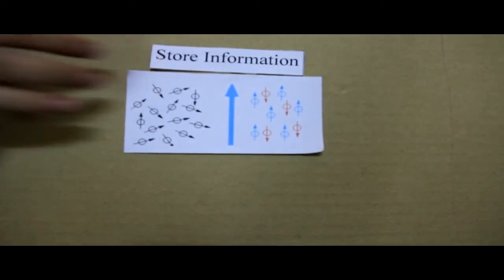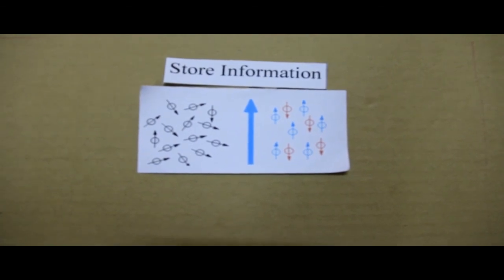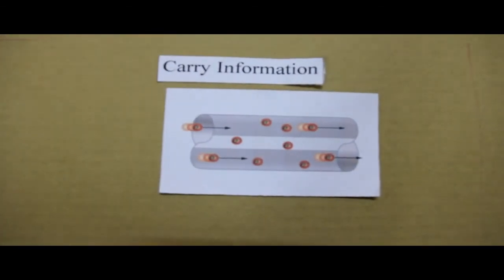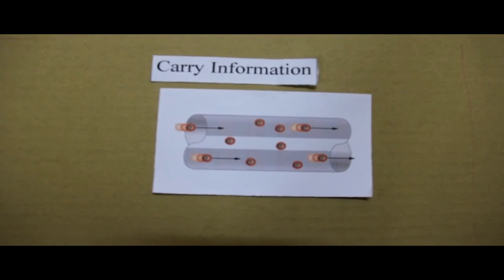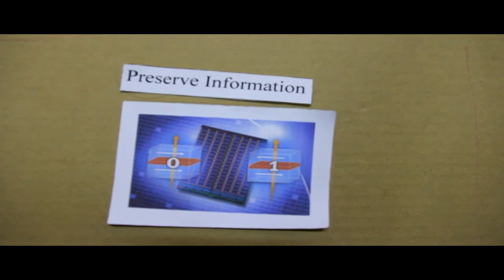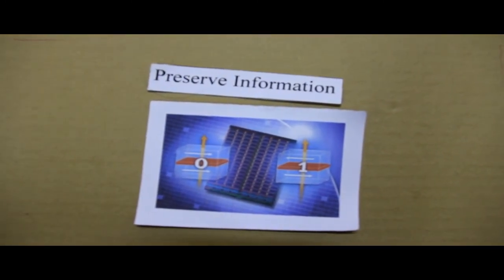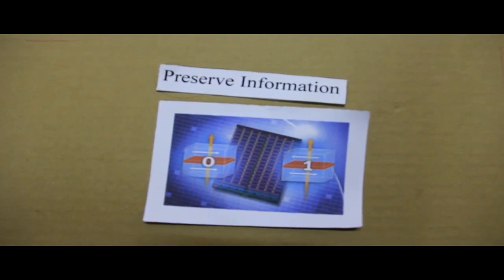All spintronic devices act according to a simple scheme. Information is stored or written into spins as a particular spin orientation, either up or down. The spins, being attached to mobile electrons, carry the information along a wire. Spin orientation of conduction electrons survives for a relatively long time, which makes spintronic devices particularly attractive for memory storage applications and quantum computing, where electron spin would represent a bit of information.